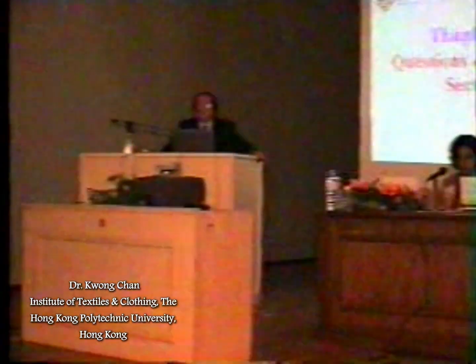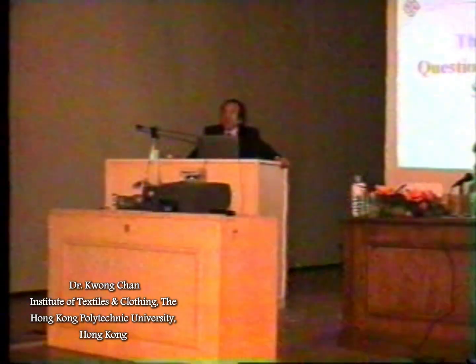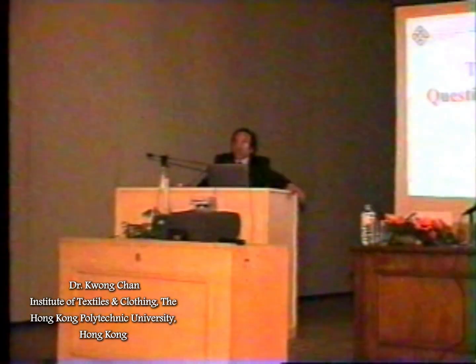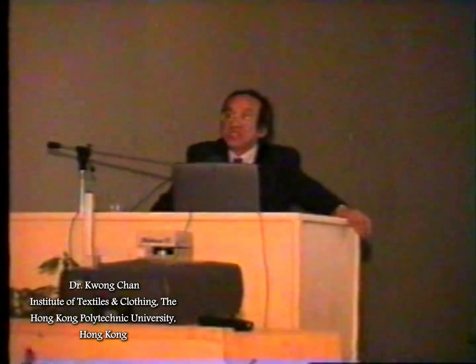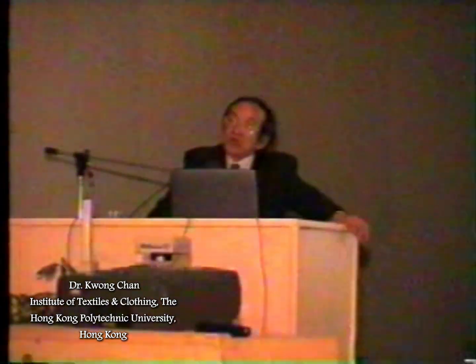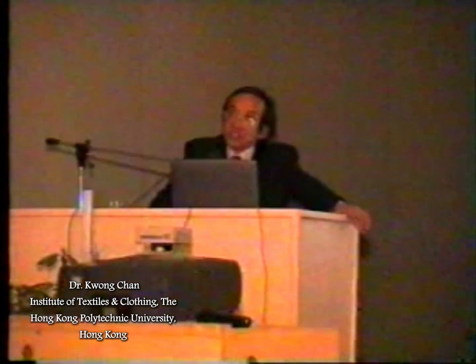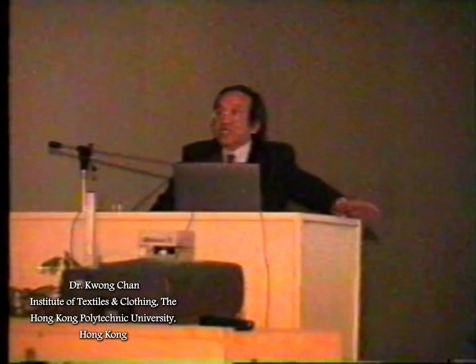Is there any possibility, the gentleman was asking, is it a chemical or physical cause of the increase of hydrophilicity? Actually, this is the laser effect which generates heat, a thermal effect, and also, as we found, the increase of oxygen groups and so on will affect the chemical nature of the fiber. So the hydrophobicity of the polymer can be reduced and changed to hydrophilicity. So you can say this can be a physically induced chemical effect on the material.